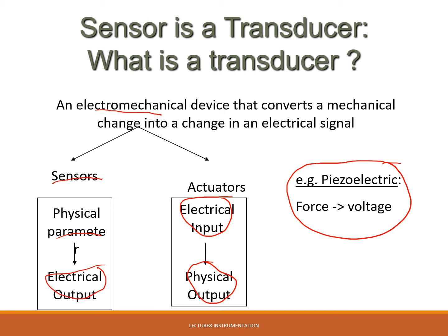When we apply force, it will give us voltage. So when in this mode, we design it as a sensor. But then we are also able to supply voltage to the piezoelectric material, and it will convert into displacement.